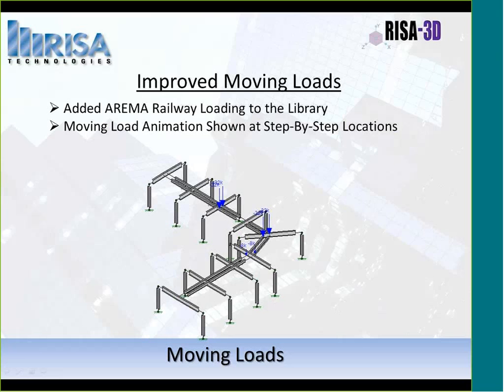It's really powerful to be able to see how the loads are coming across your structure. But what also is new now is that you can slow that down and see it stepwise. What we call that is increments or steps, and we can apply the increment that we want to be looking at. So for example, this might be a couple hundred increments along the member that we're looking at below there, and we can look exactly at that increment.